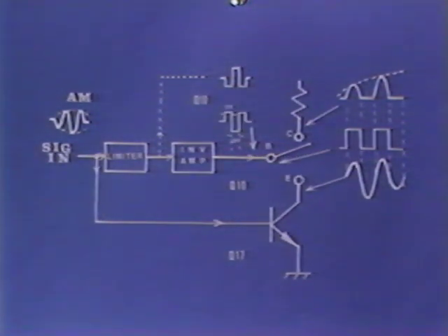Synchronous detector. The detector is the mechanism to pick up the original R and B primary color signals by detecting each of the separated R and B AM waves from the R and B separator. JVC GXV7 employs the synchronous detector for its linearity and for its consideration for the power supply's regulation.